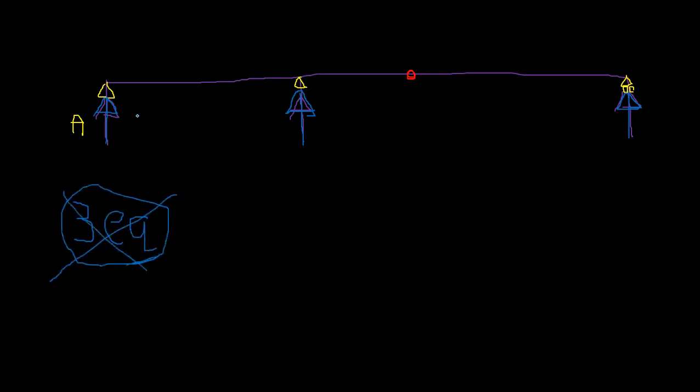But can you use all three? No, because your horizontal loading is 0. So that means you cannot use the horizontal equation as well. In that case, you can only have 2 equations. So 2 equations, 3 unknowns. You can't solve this. But here you have a hinge there.